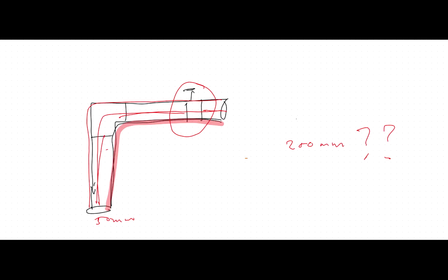That is the main reason why we need standard method of measurements. POMI says very clearly how this pipe should be measured. Even though you measured, even though I measured, even though consultant measured, even though contractor's subcontractor for MEP measured, it will be the same, right? So that is the importance of why we need method of measurements. I think you got an idea, right?